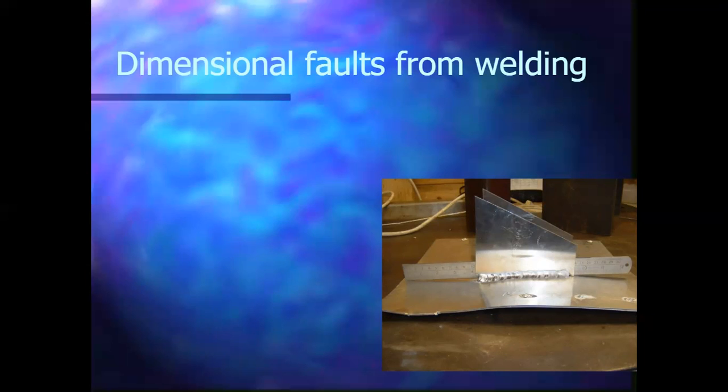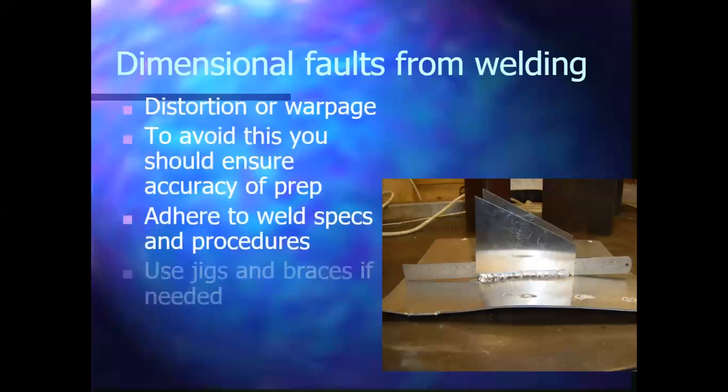And then we got to look at our application. I don't know what this is being used for, but the question I'm going to ask is, do we have to weld the whole thing? Do we have to have that much weld on it? If not, then we don't need to put that much weld on it, because more weld equals more heat and more distortion. If this is just something that needs to sit there for a little bit, put a little tack on either end, maybe a 1-inch stitch on it, it'll hold it there just fine. If it has to be welded fully, then we got to look at other ways of controlling the heat input. It could be securing the plate, could be clamping it down, could be stress relieving after the fact. There's a bunch of options here, but yeah, we got distortion, we got warpage, we got all sorts of things.